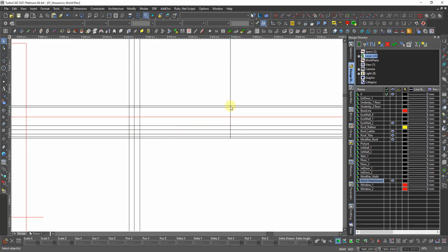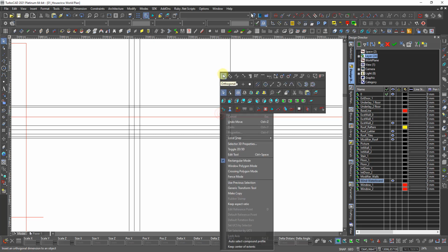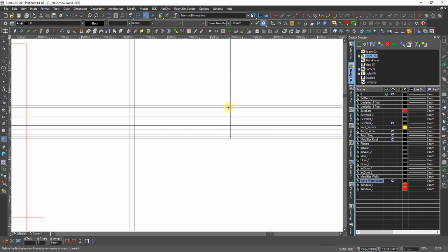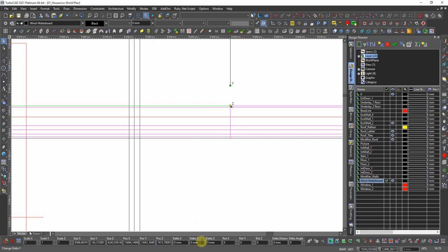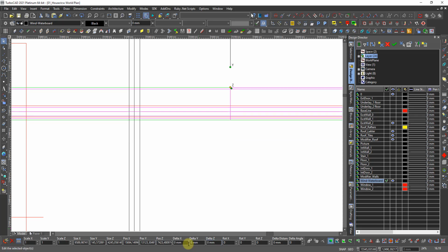But from that edge to in here, there is now from nearest to nearest 82. So move this delta Y 82, and then move it also up 7 millimeter. 5 by 1.414 is 7.7 something. 7.7 like this.